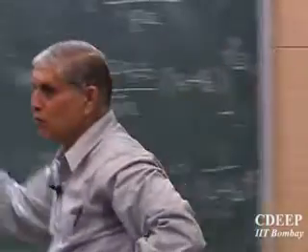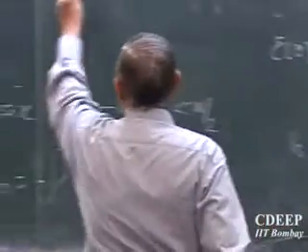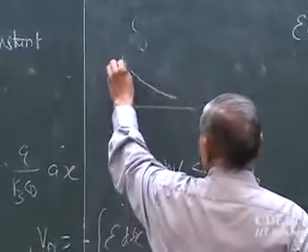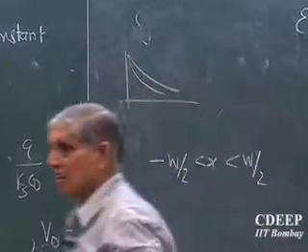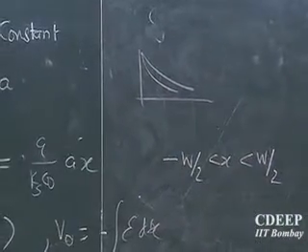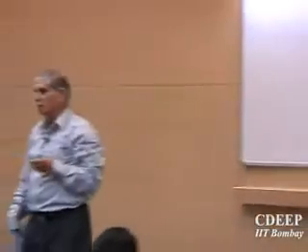So you are looking for those characteristics. You see that? So for the same VR, the upper one will be the linear graded junction, the lower will be the abrupt junction. Is that clear? So you must have thought, how do I go about it? One way is to change NA and ND, the other is to have a linearly graded junction, in which case you may have slower variations.